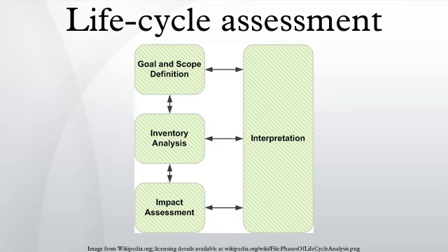This is accomplished by identifying the data elements that contribute significantly to each impact category, evaluating the sensitivity of these significant data elements, assessing the completeness and consistency of the study, and drawing conclusions and recommendations based on a clear understanding of how the LCA was conducted and the results were developed.